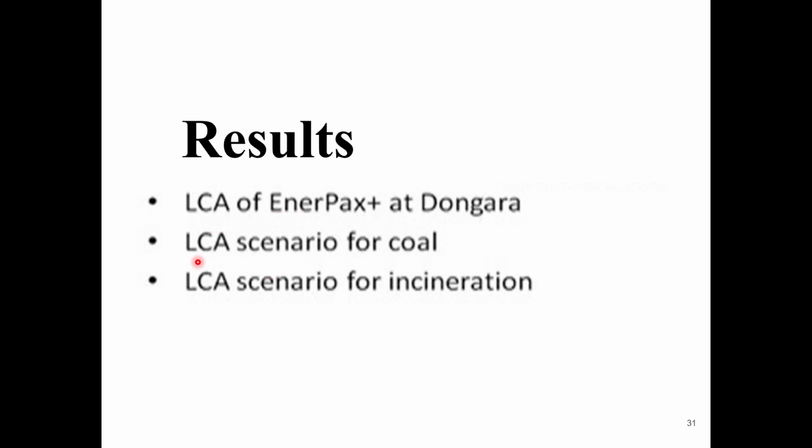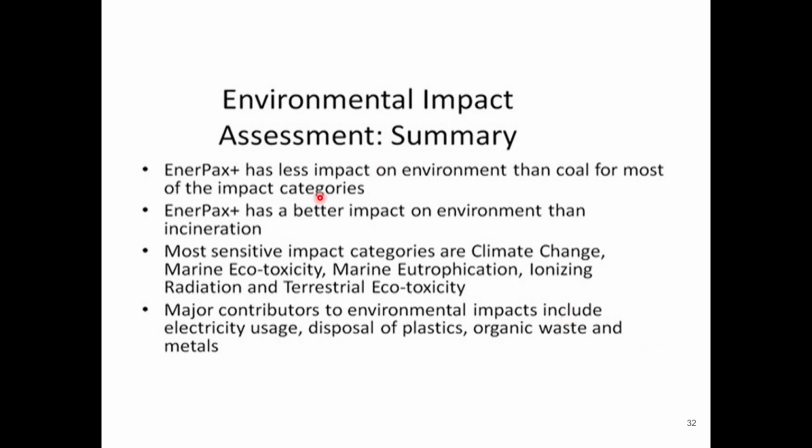So results, we saw the LCA of NRPX plus at Dongara, LCA scenario for coal and LCA scenario for incineration. The environmental impact assessment summary can be such that NRPX plus has less impact on environment than coal for most of the impact categories. NRPX plus has a better impact on environment than incineration. Most sensitive impact categories are climate change, marine ecotoxicity, marine eutrophication, ionizing radiation, and terrestrial ecotoxicity. And major contributors to environmental impacts include electricity usage, disposal of plastics, organic waste, and metals.